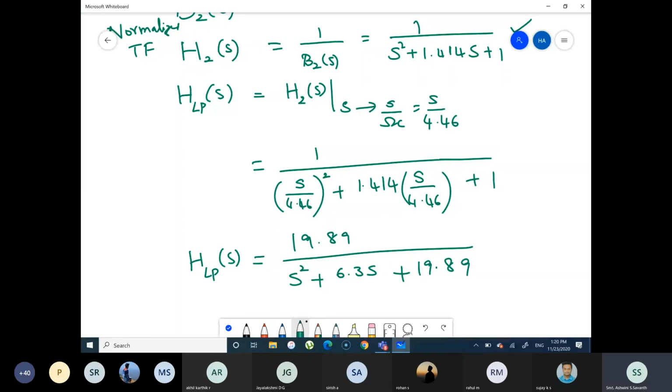So we are writing the transfer function, correct? Not the filter coefficients like we did in the FIR filter. We are obtaining the transfer function here, and you know that once you obtain the transfer function, you can also find the filter coefficients. It doesn't matter, either one of them is fine. Filter coefficients, that is h of n, or the transfer function, or the frequency response, if you find any one, we can convert that to the other.